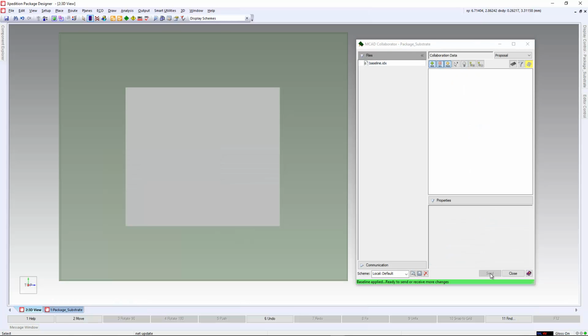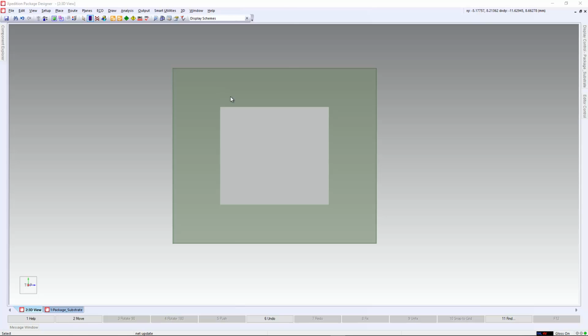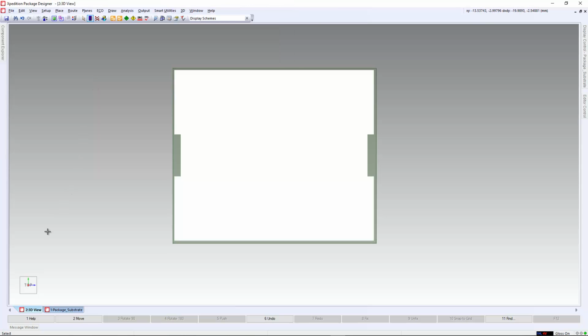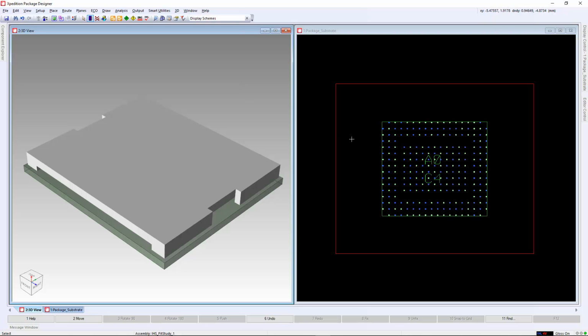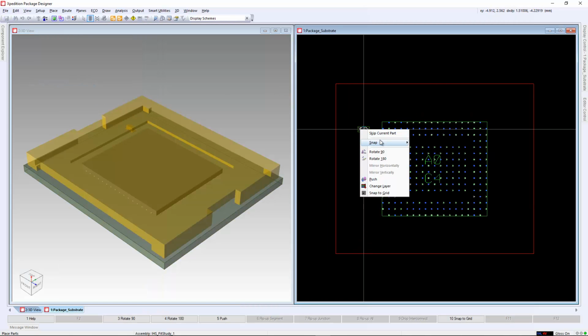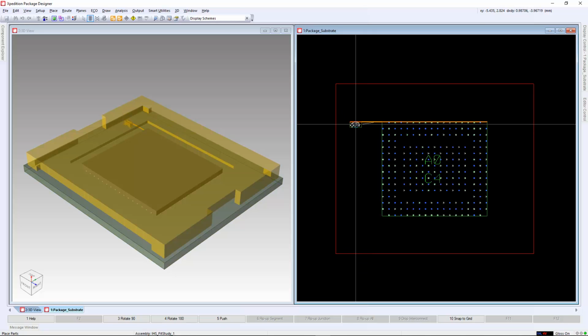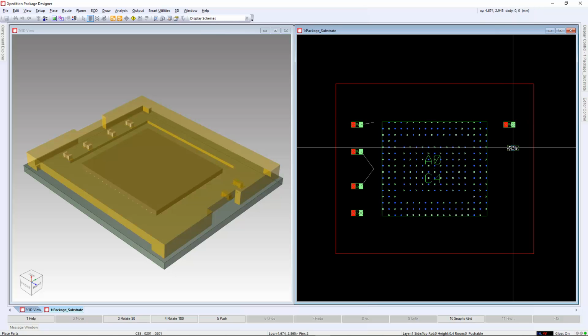In this example, we will be collaborating between Xpedition Package Designer and Siemens NX to show how to realize the digital twin. Typical collaboration between ECAD and MCAD starts within the mechanical world. The mechanical designer will create the substrate outline, dies, epoxies, and an initial enclosure to test the spacing requirements. A baseline file will be created to synchronize the mechanical and electrical data. This will synchronize the ECAD and MCAD objects, so subsequent changes will only contain the modified data.